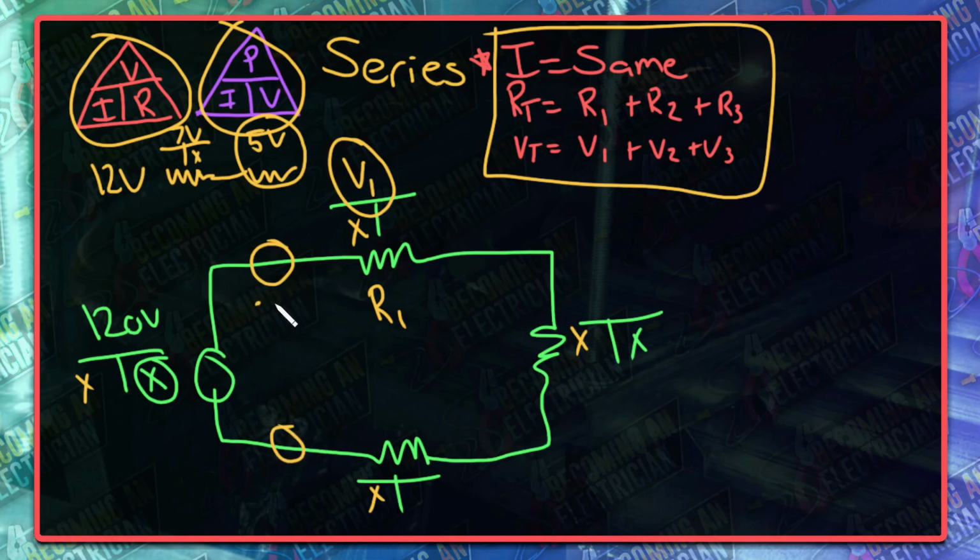So let's just say this was like 0.15 ohms, then you would actually have 0.3 total ohms of resistance just off of your wires. And that's to do with what's called voltage drop. And sometimes you have to upsize your wire. So for example, if you had a number 14, if it would give too much voltage drop, then you might have to upsize to like a number 12, or number 8 or number 10 or whatever. You're going to have to upsize the wire to get less resistance, even though the load can easily handle it.